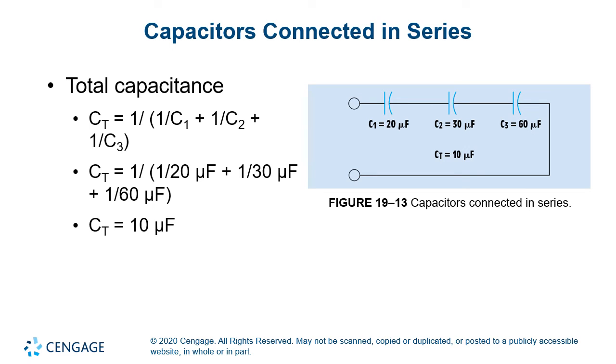On the other hand, when we connect capacitors in series, one after the other, they actually cannot increase the capacitance. They actually limit the capacitance between them. And for calculating, we use that reciprocal relationship, similar to how we calculated resistors in parallel.